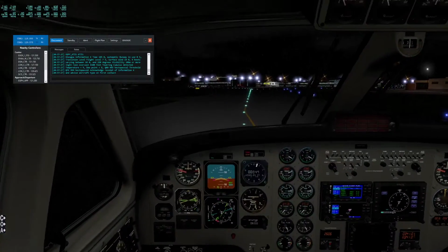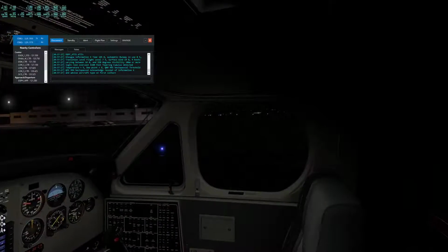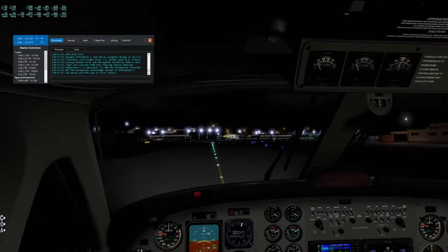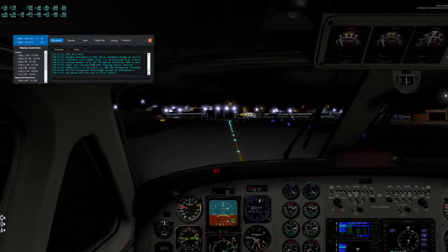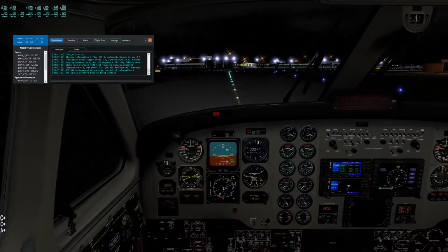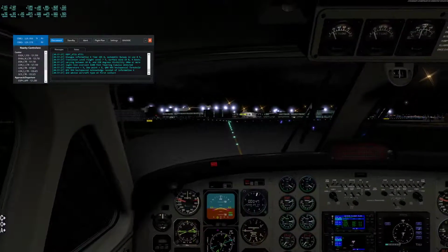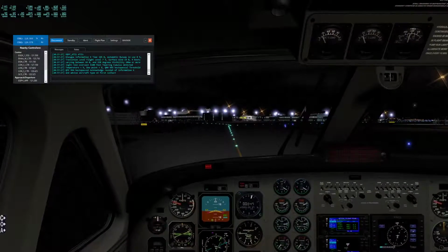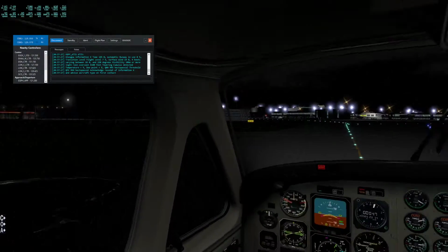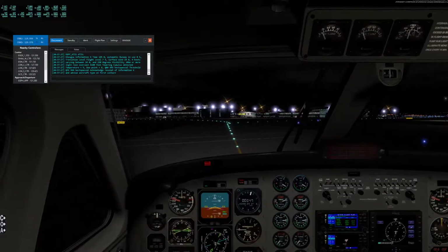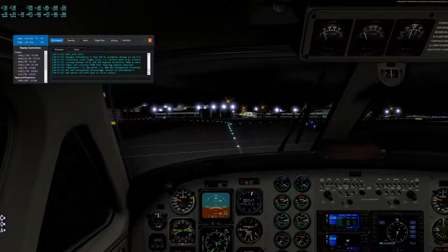In the real world you'd have to properly know your minimum takeoff distance. You'd also want to look properly at the airport chart and consider, especially the type of aircraft you're in, that you might be given the option to depart on a shorter segment of the runway. So have all that worked out in advance, and don't just panic when you're asked, can you do it, and then say yes. In this case it's fine, but a bit more planning would have helped.